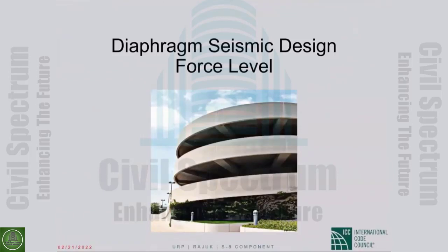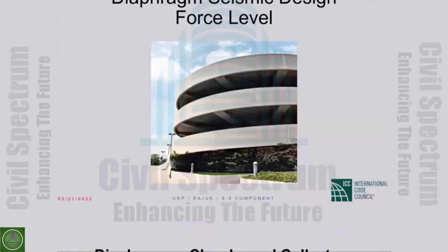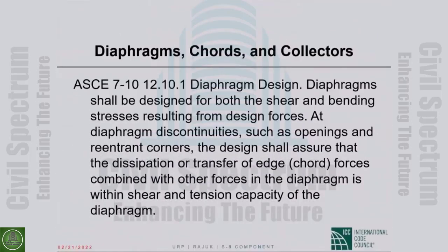Now we come to diaphragm seismic design force level, which has been a pretty hot topic in recent years. So I go to ASCE 7-10, section 12.10.1, ASCE 7-05 also had 12.10.1, a very important section on diaphragm design. This is where you come for the design of your diaphragm. And diaphragms have to be designed.